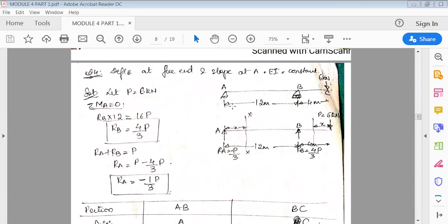Okay. So here ABC is an overhanging beam wherein there is a point load at C. So they have asked us to find the deflection at the free end only, that is at point C. Now there is already a load here, so no need to apply any dummy load because this is the vertical load. To find the vertical deflection, we already have a point load here. Now, we have the formula of Castigliano's theorem. That means you have to have P in it.